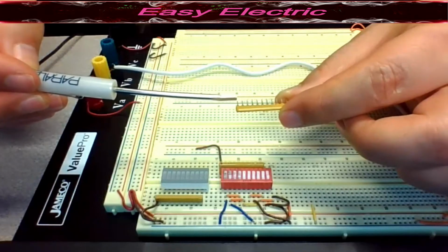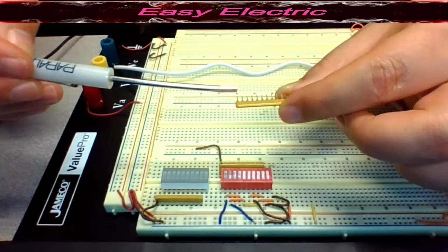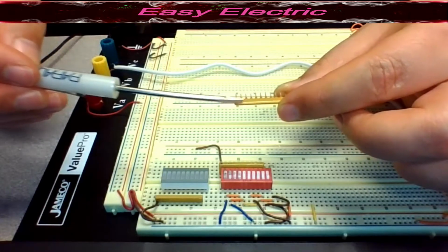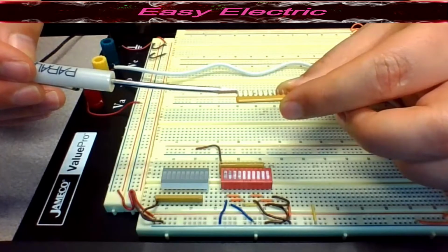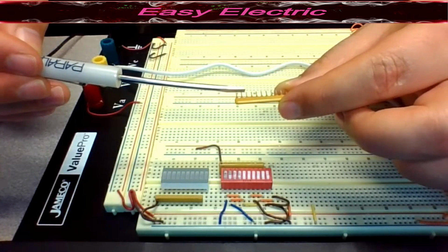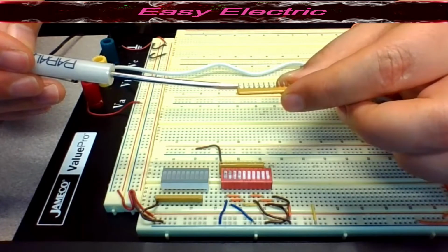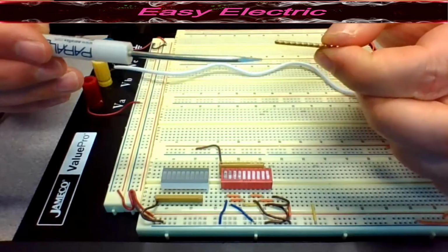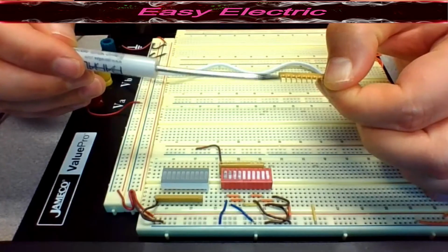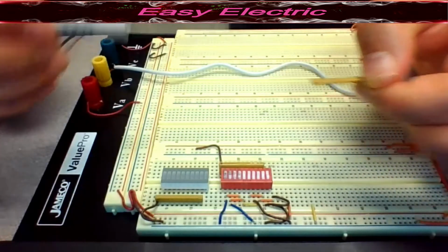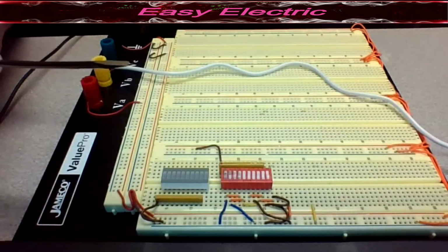So how could you use that? You could use the common pin and any of the other pins. For example, if this is a 1K resistor bar, the resistance between the common and each of these pins is just 1K. Usually there is a mark here so you know which one is the common, and you actually use all of them, as we use these two resistor bars here.